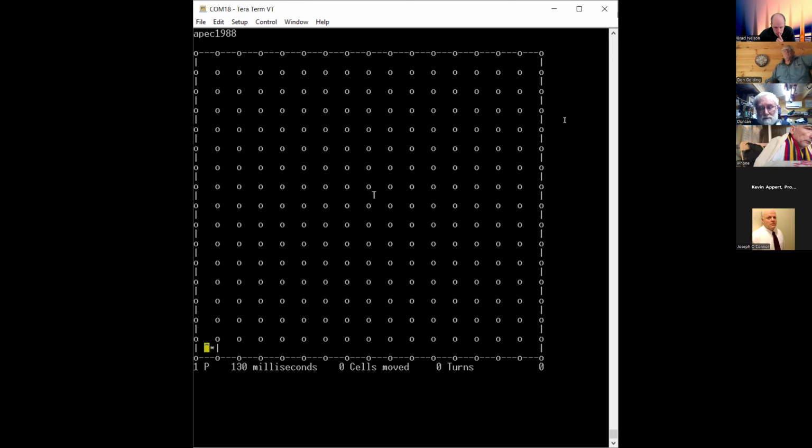And then from then on, I keep taking things out of the queue and going around the 4 adjacent cells. And if there's no wall, it checks to see if the mouse is in the adjacent cell. And if it is, you move the mouse into the target cell and you finish. That's great. If the mouse isn't in the adjacent cell, it puts that cell into the queue and marks it as solved.